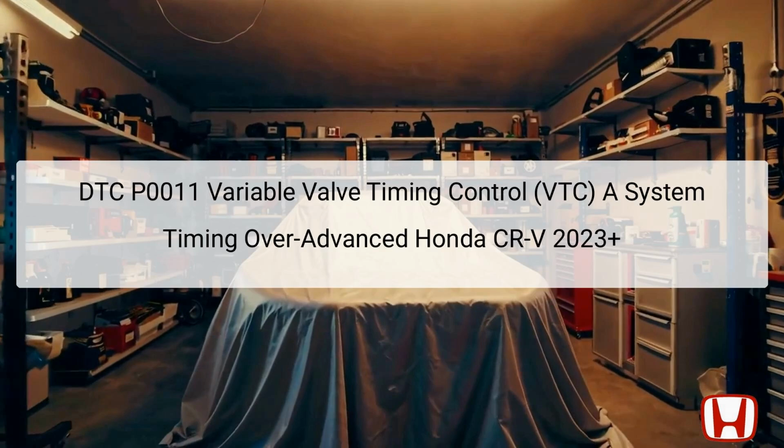The diagnostic trouble code, DTC P0011, indicates an issue with the variable valve timing control, VTC system, in the Honda CR-V 2023 and later models. This code is triggered when the advanced intake camshaft phase angle exceeds the commanded value, leading the powertrain control module, PCM, to identify this anomaly and store the DTC.